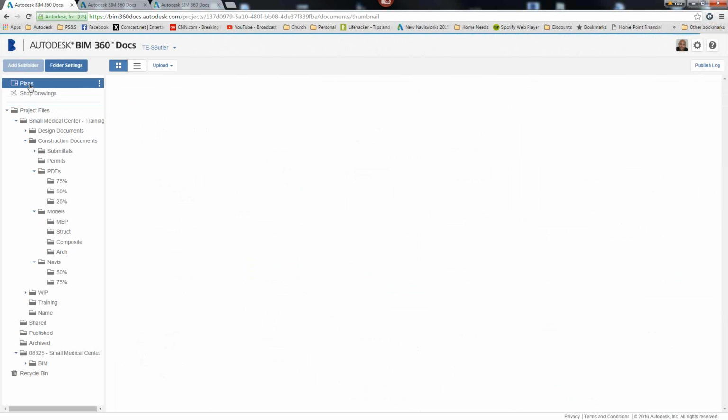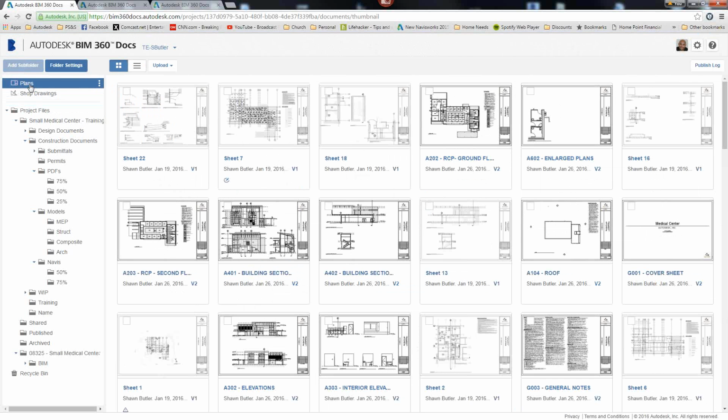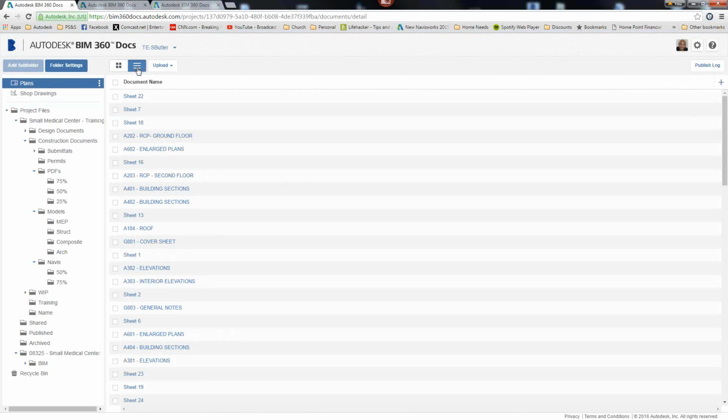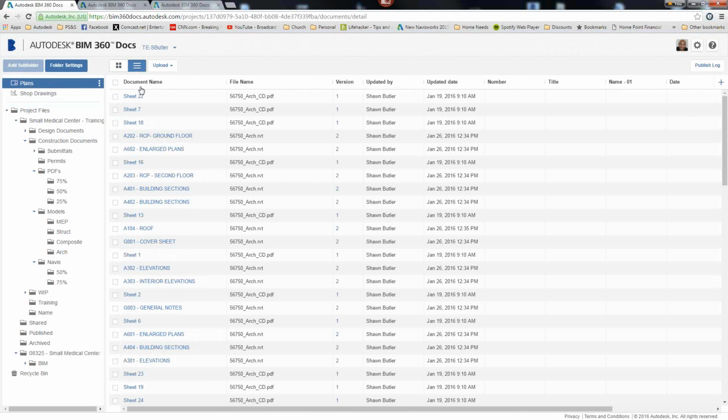With those attributes, once again, easy setup to go through. Within our document view, when we look at our detailed view, here are those attributes that we were talking about. You can come in and simply by using the plus, we can go through, and now you can start to add custom attributes. You can turn those on or off simply by clicking at them. So again, this is something that you can load in, come in, set those up to the title blocks for your project, and now you have that information stored.